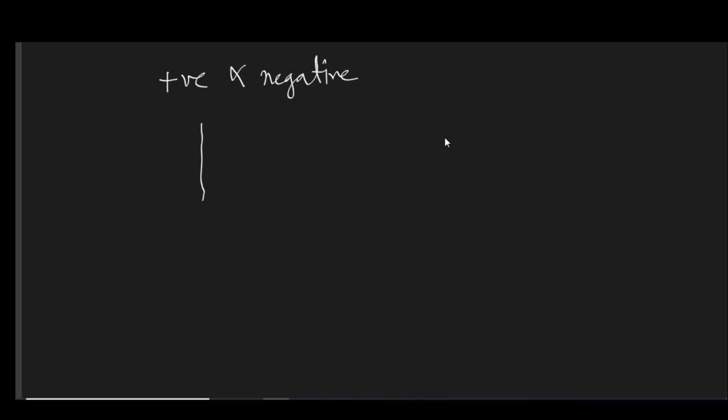If you have a star connected network like this and you connect one ammeter with the ground, then unless you have any zero sequence component present in your phase current, this ammeter will always read 0.